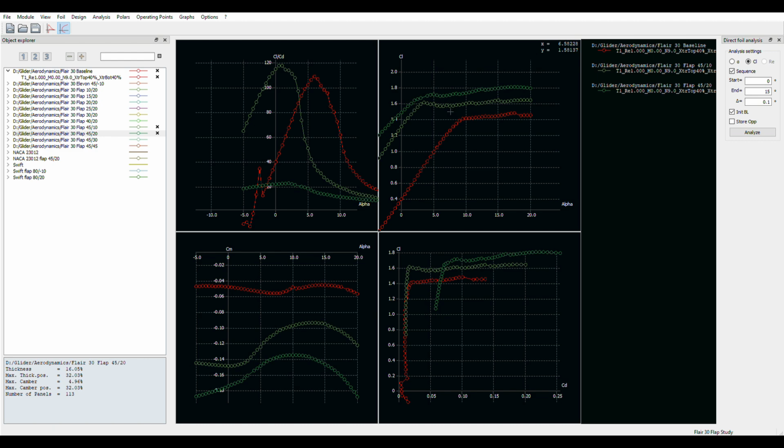You're pulling lift, but the nose doesn't go down a lot, but it doesn't go up, and you certainly don't slow up, and your lift curve has gone up. Let's see, which one do I have turned on? Yeah, that's the right one. But your stall angle of attack has gone way down.